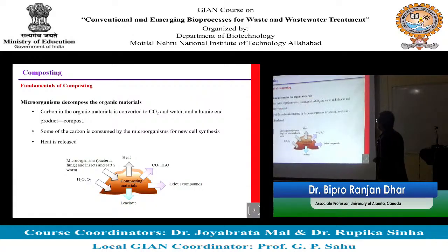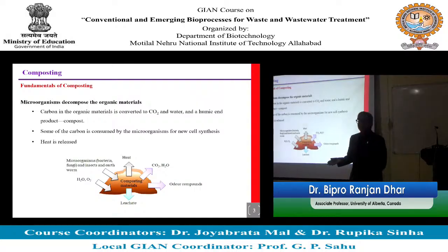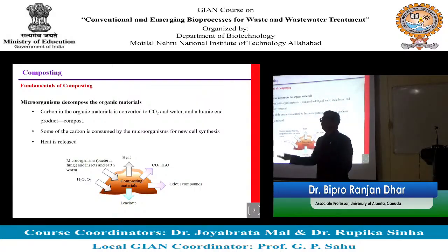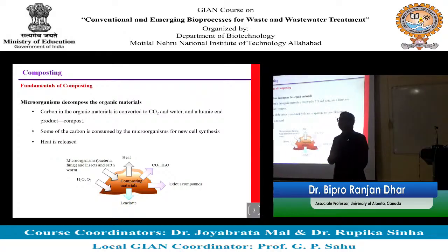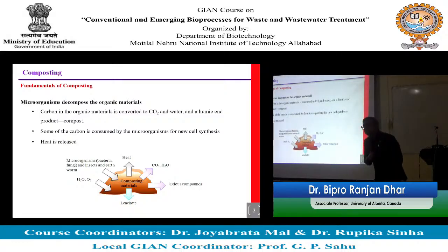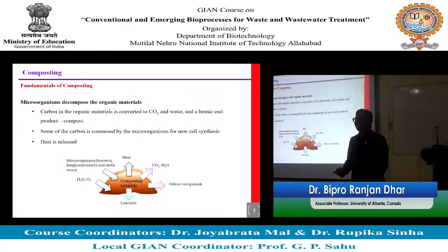That means like the aerobic activated sludge process, in the composting process we also need to provide air, because those microbes need oxygen as electron acceptor. You remember that, that's good. So we need oxygen in the process, and the process is going to produce carbon dioxide, water, and release heat, but at the same time some odorous compounds can also be generated, like ammonia and sulfide.